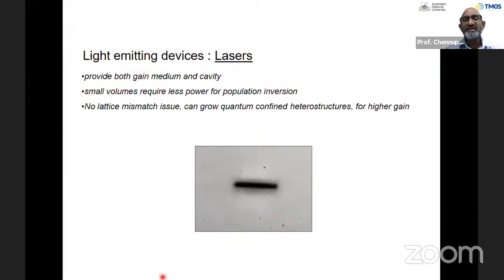Now it turns out that if you take these nanowires and shine light from the top, and you choose the right kind of nanowires, they act like waveguides. Light propagates through the nanowires and comes out of both ends. These nanowires have a refractive index of 3.4, and air has a refractive index of 1. Because of this, both ends of the nanowires also act like mirrors. So I really don't need to create any separate mirrors or cavity. In principle, each nanowire should act like a laser cavity, and if everything goes right, I can make each one a laser.